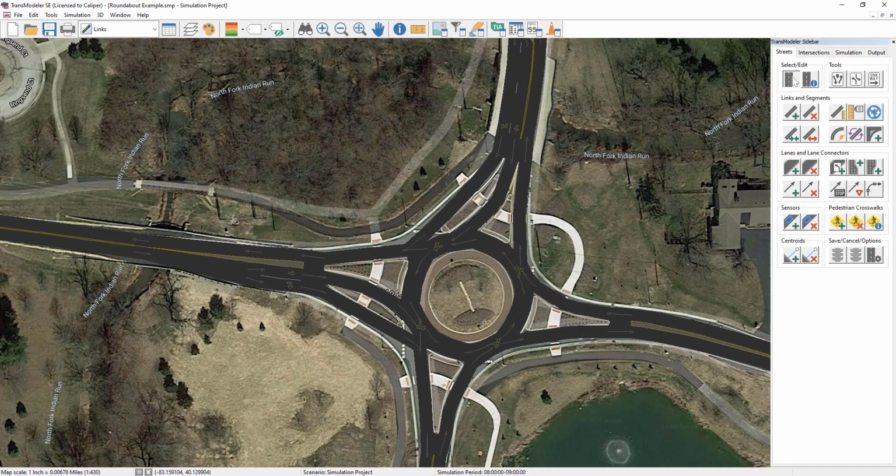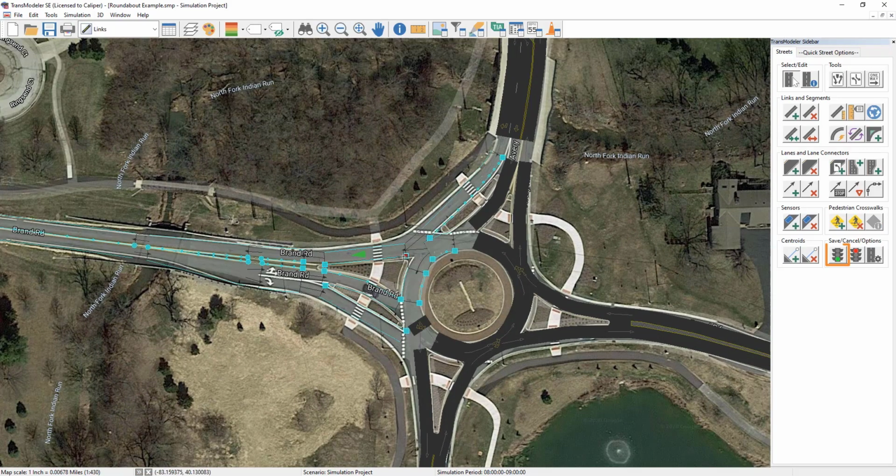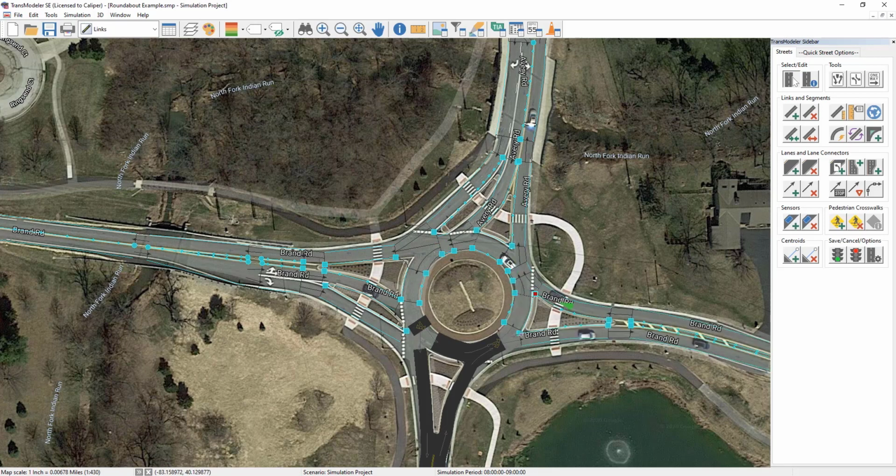Once all the appropriate edits detailed in the previous steps are applied, check over the whole roundabout configuration one last time. If further refinements are needed to add curvature at any links, add or reposition the intermediate shape points as needed.